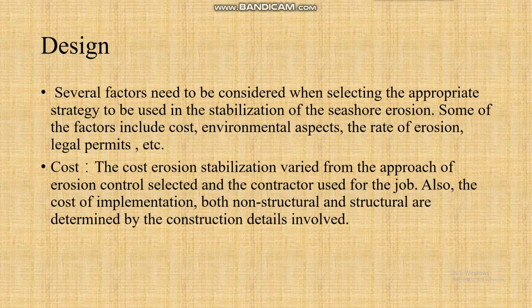And for the design, we have to consider several factors when we're selecting the appropriate strategy to be used in the stabilization of the seashore erosion. Some of the factors include cost, environmental aspects, the rate of erosion, and legal permits. So the cost of erosion stabilization varies with the approach of erosion control selected and the contractor used for the job. Also the cost of implementation, but we have to consider both non-structural and structural by the construction detail.